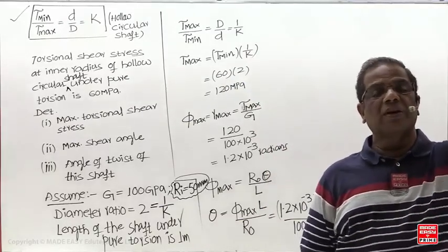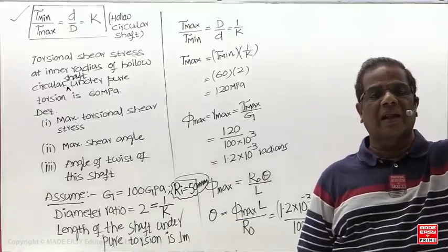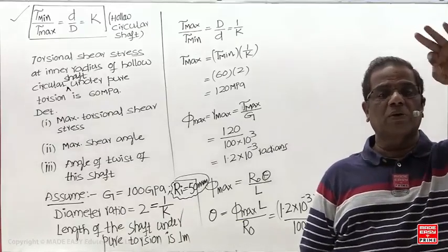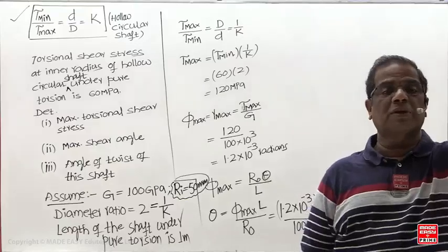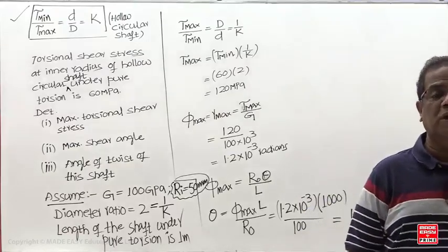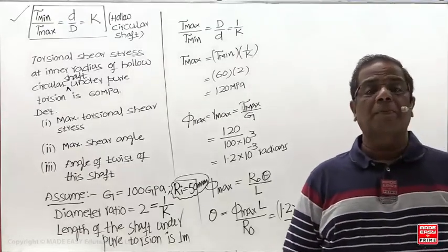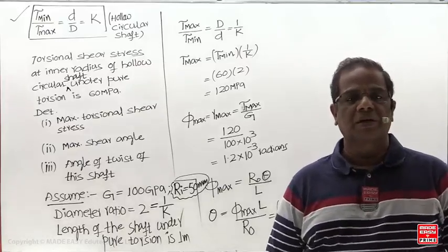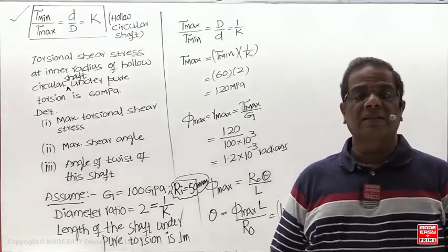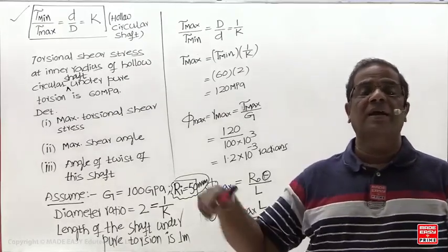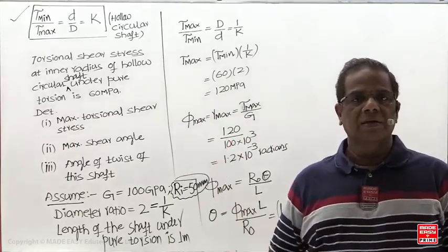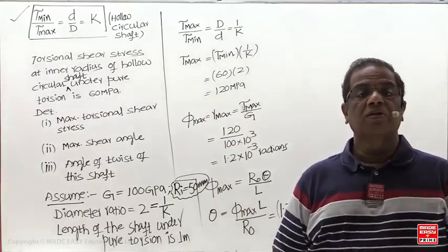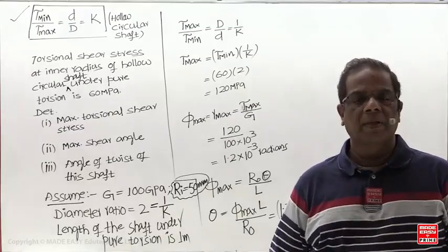So the first student is going to directly give the answer without any calculation. You will remember the simple conclusion that you have mentioned, sir: stress on the cross section is proportional to the corresponding load and inversely proportional to the corresponding geometrical property or cross sectional dimensions. So in both cases torque is same, diameter same, then the answer will be directly 100, without any calculation.